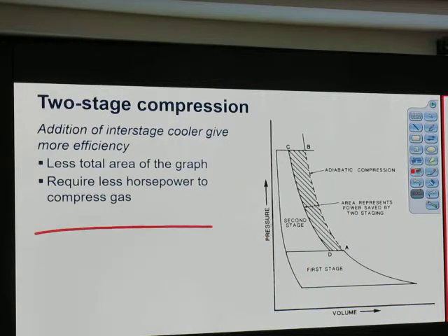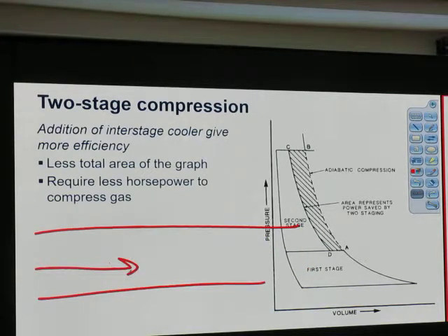If we flow it quick and we shrink it and we flow slow over here, there will be deceleration pressure gain. But those things are negligible compared to the amount of energy or force that you put in. So the accelerational pressure gain is not much, we neglect it. The only time it is kind of significant is below 100 psi. For the compressor calculation, they neglect that. Does that answer your question?